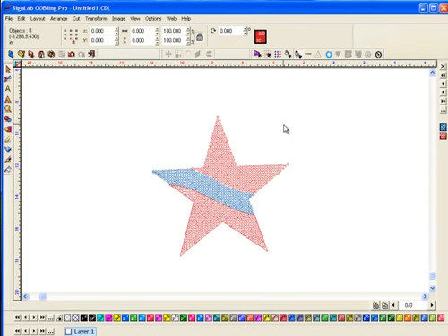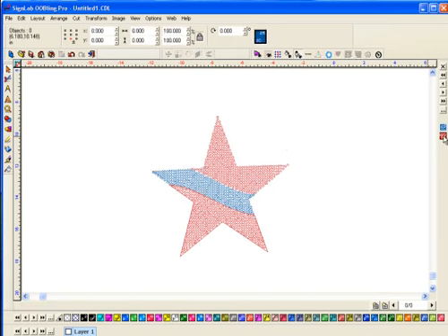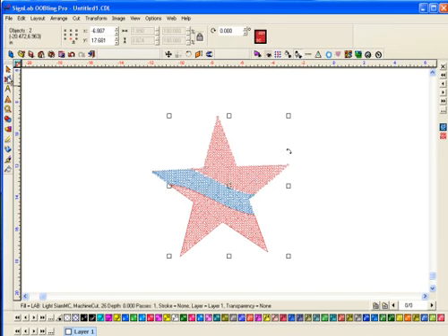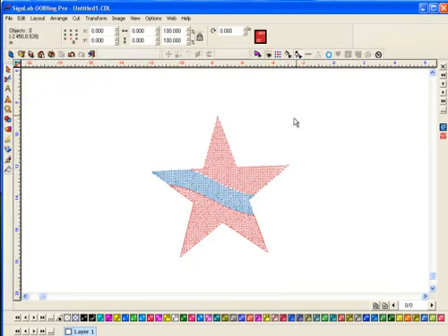And what you would do now, when you go into cut, if you're ready to cut this design, you're going to cut it into two templates. You can either double-click this and it selects all the blues. You can click on cut and it'll only cut this pattern. And after you're done cutting that, you close that, double-click the red one, go to cut, and it would only cut this pattern. And basically that's how you would do this. I'll show you one other technique.